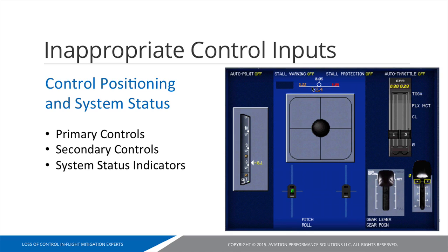In this particular chart here we can see this is the airplane's wing. This is the fuselage load in this particular situation. This is the tail load. This is now the wing load on each side. So for example, in this particular maneuver, it was clearly a rolling pull near the limit load of the airplane on the fuselage, but that upgoing wing, that rolling wing, exceeded the limit load. We can see here that it had turned red. It exceeded 2.5 G. So it's a cue to the instructor to understand different areas that are being exceeded.